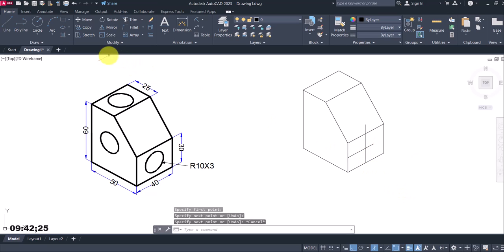Okay, so this is going to be the middle point of that circle for me. So I can now pick ISO circle, center point. Fortunately, this is giving me the right plane. So now radius of 10. Okay, so that's my first ISO circle. I'm going to do a little bit of construction here too. Now F5. Oh no, I've snapped in the wrong direction. Middle points. Okay, so this is going to be the center of the second circle. ISO circle, center point, radius 10.